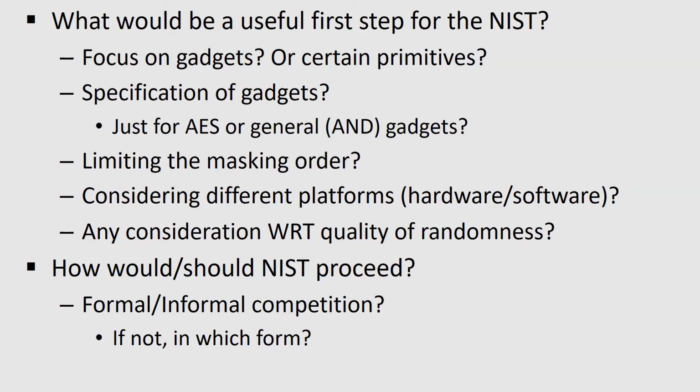or I have very little flexibility to optimize to achieve certain trade-offs, as I said, for area or performance or power, because I will always have, let's say, the S-box, which has to be implemented in 10 cycles. And I cannot do better than that. For example, I cannot do a cubic function or a bit more complex function. I have no such gadgets which directly do the job. I have to obey the AND gates and the decomposition like that. Maybe it's a stupid example at the moment, but it's the first one that came to my mind. And that's why I say flexibility matters. Not all products will have the same requirements, certainly.